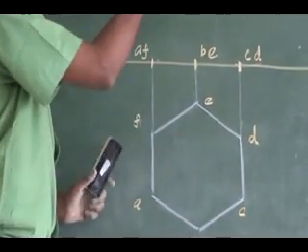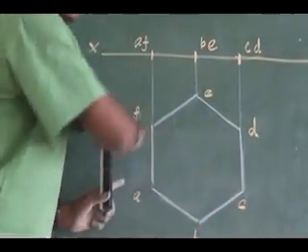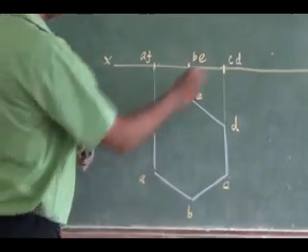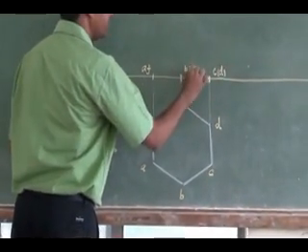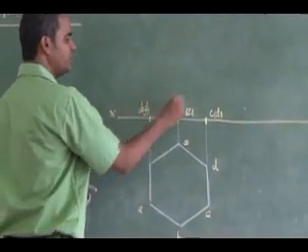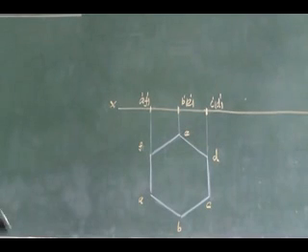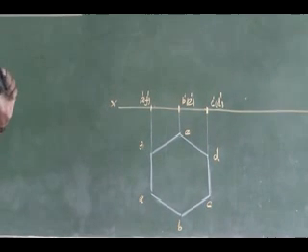So to put brackets for the front view, look at the top view from the bottom. I can see ABC, I cannot see FED, right? So D is hidden, E is hidden, F is hidden. So these are all notations with dash, these are all front view notations. Right. Now this is my first step, the assumption step.